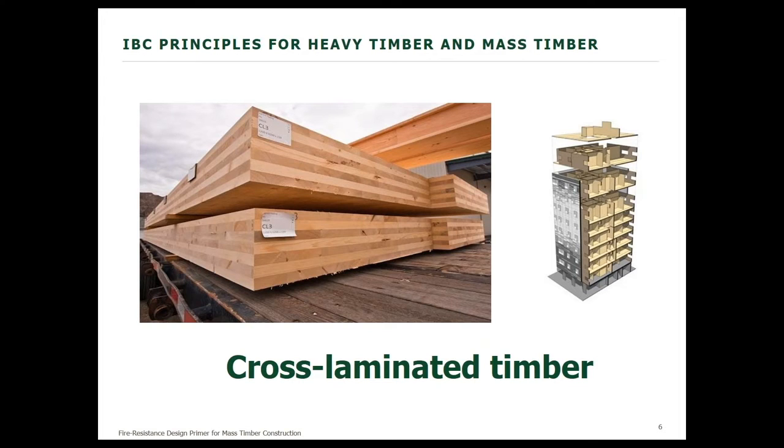It will enable taller buildings far beyond the normal capabilities of repetitive member systems of traditional or engineered joists, studs, and rafters. And it will also have very different fire resistance characteristics that come along with its mass: the reduction of wood surfaces in solid wood assemblies as opposed to repetitive member assemblies, and the way it will respond to fire.